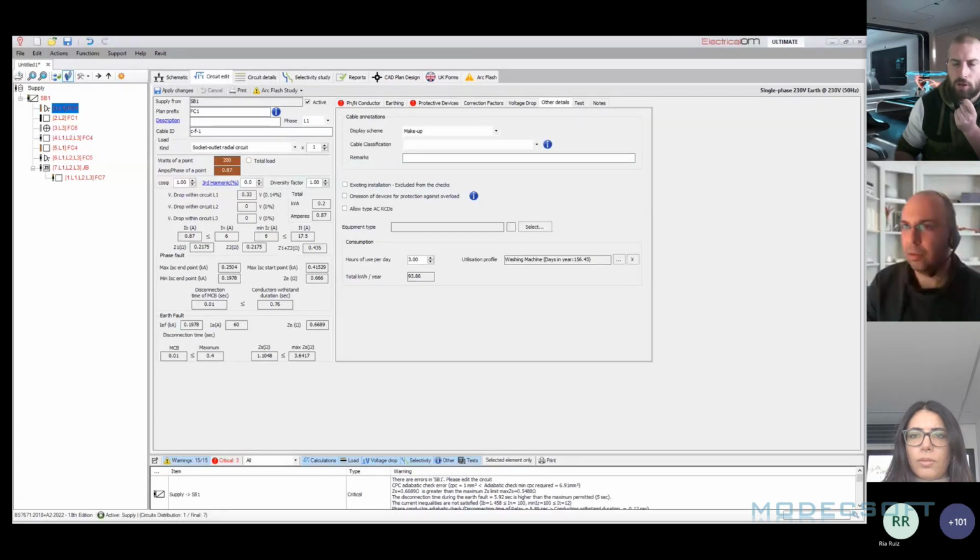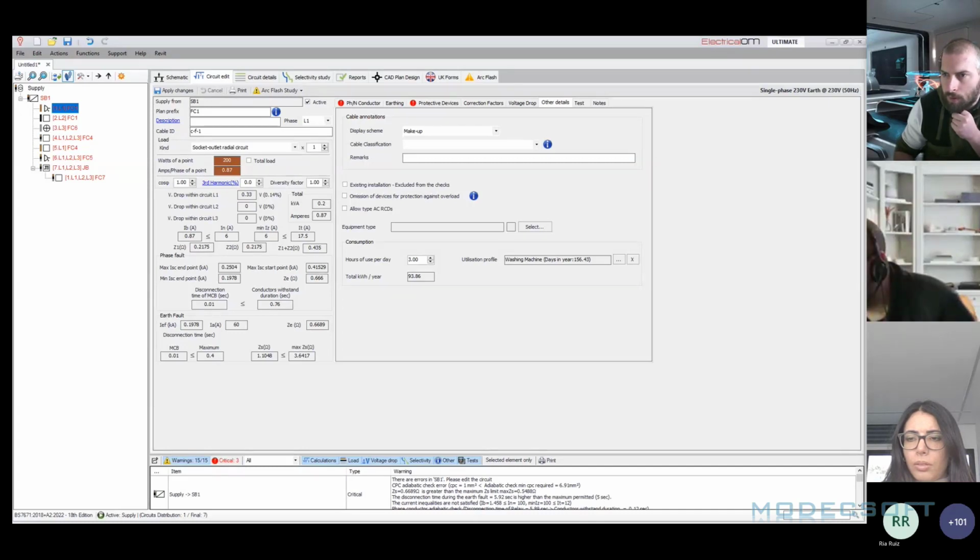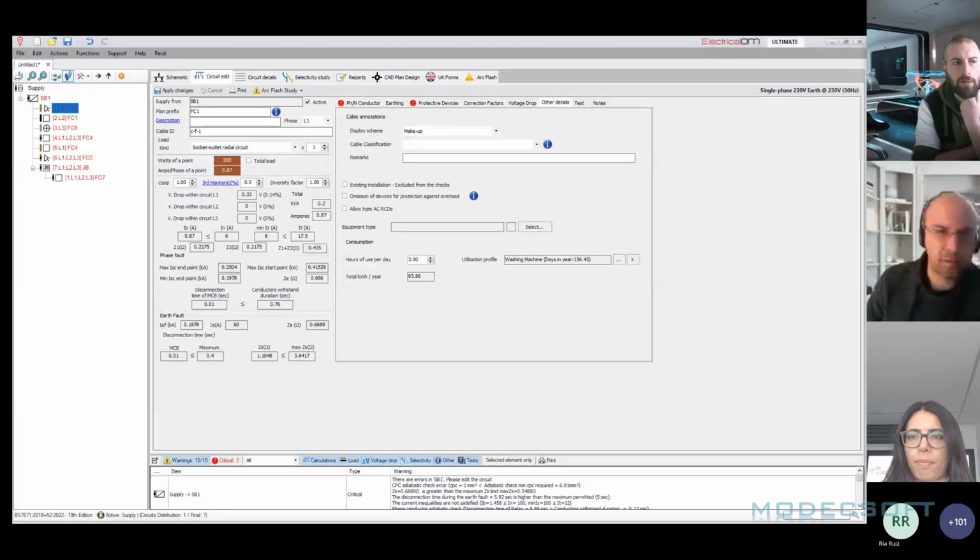In terms of the consumption ones, no, it's all manual at the moment. You would create your own consumptions, and use it for the analysis in kilowatt hours per year. Possibly diversity was being asked about, which you can put in manually in your system. If it's diversity, then we do have the standardized tables from the likes of the IET Guidance Note 1 already pre-built in there for diversity factors and those sorts of things.